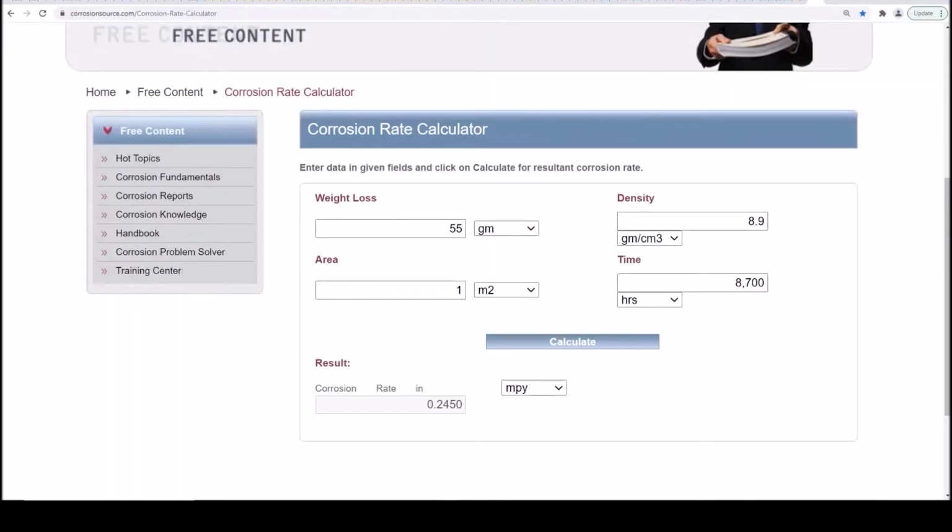Of, let's say, 100 grams, because let's say you got to 0.10. So if you get to 0.10 mpy as a target, then let's say you have 0.11, that gives you 25 grams of material lost a year for 1 square meter. If you take 10% loss a year as acceptable, you take 25 divided by 10%, you need 250 grams per square meter to achieve that loss of 10% a year. So in other words, you need at least 250 grams of electrode for 1 square meter.